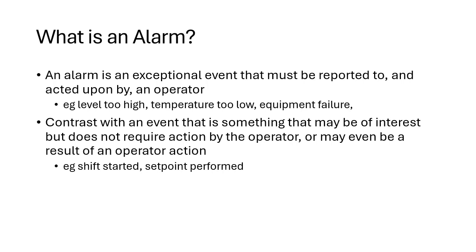An event is something that may be of interest but does not require action by the operator, or it may even be the result of an operator action. For example, the shift has started, a set point is performed, or some other operation that would be a normal part of the equipment operation that's interesting and needs to be logged or reported on, but doesn't actually need to be acted on specifically by the operator.